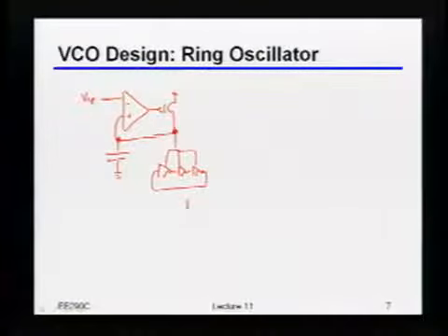Locks to a metastable point. Okay, so you said it locks to a metastable point. So now I'm going to put on my digital hat. That's true, but what was the criterion that I broke? Why did it lock to a metastable point rather than oscillating? The digital discipline. You're hanging out in the forbidden zone.